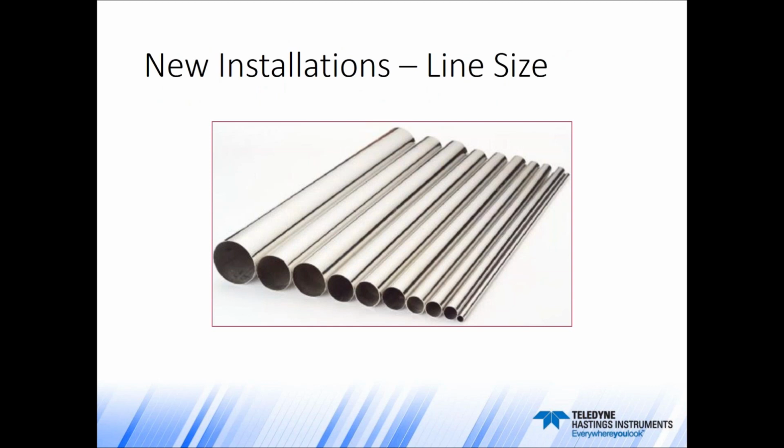Users must always ensure that they have the correct line size for the expected flow rate. As an extreme example, you're not going to be able to get hundreds of standard liters a minute of flow through a 1/4 inch line. In general, the fittings that are available for a particular flow controller, like you see on our product bulletins, will point you in the right direction towards selection of the correct line size.